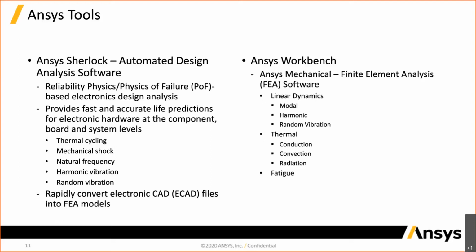And from there, you can run all these different analyses. You can do the thermal cycling, the solder fatigue. You can do mechanical shock. You can do a modal analysis or natural frequency analysis, or you can do a harmonic vibe and the random vibe.